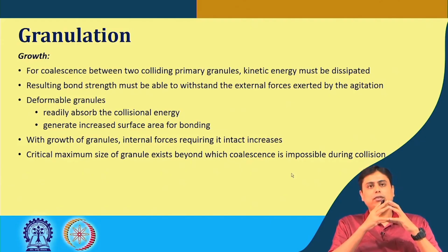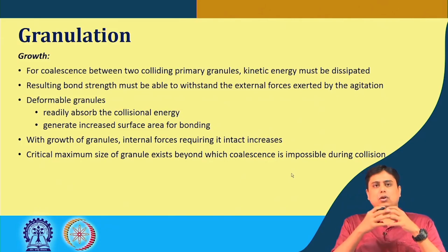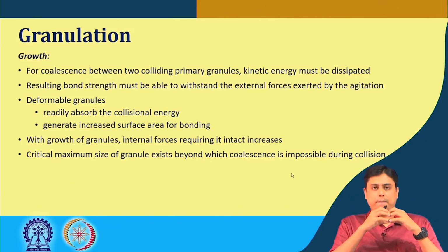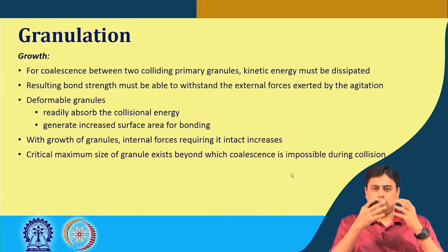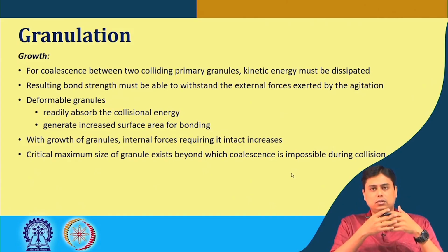Now, in the case of deformable granules, that means if the surfaces can be deformed during the collision, they can readily absorb the collision energy and generate increased surface area for the bonding to happen. Now, with the growth of the granule, it requires more and more internal force to keep it intact.